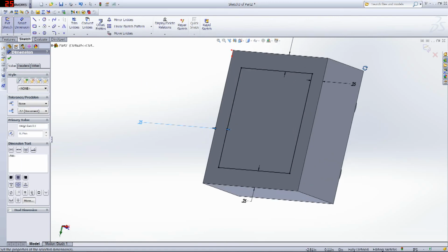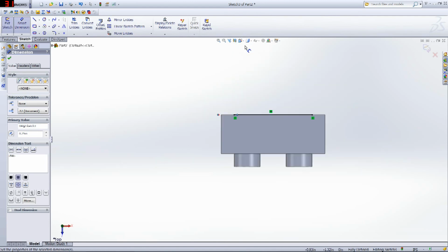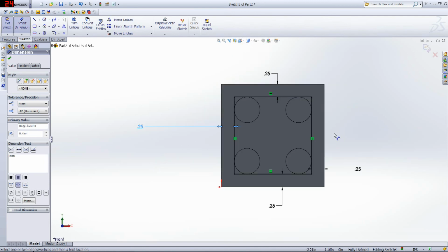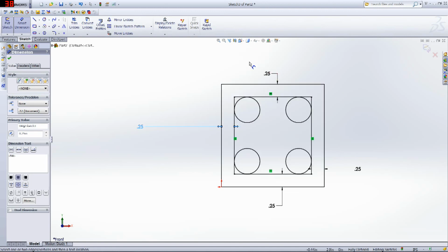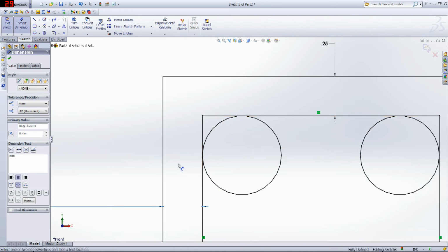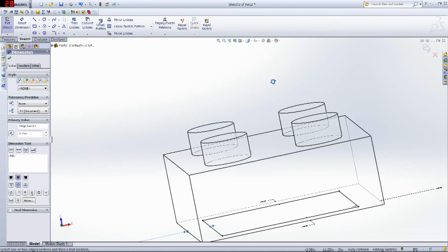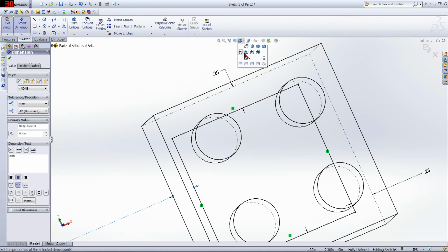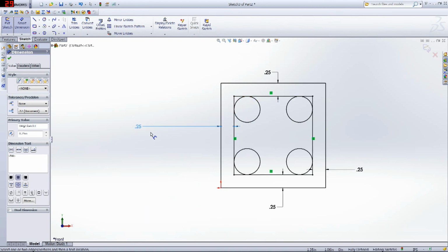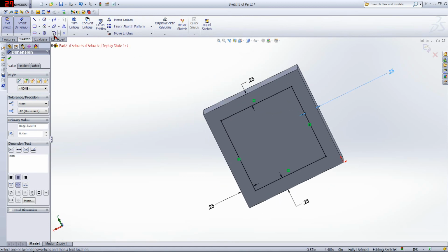So now that these edges are all 0.25, you need to fill the edges, because as you can see here from the top view, let me change this here. There's only 2 points of contact per circle on the current setup. So if you cut that hole, there's going to be 2 points where the circles actually touch, and we want as much stability as possible. So when you go to the back, you want to fillet the edges.